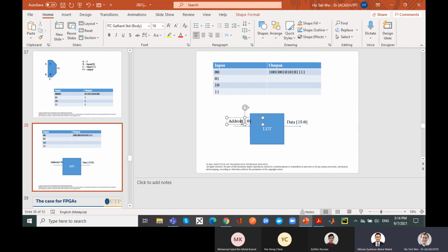Register, Doctor. Register, it looks like a form of ROM or memory, right? Not quite register. Register is actually another word for a single flip-flop, but you are on the right track. This actually looks to you something like, I think your word is ROM, because you can't write it, right? It's already saved, or it's a kind of memory, all right? It's a kind of memory, right? You put in the address, the data. So you can actually implement a lookup table with a ROM device or a memory, correct? You use the inputs as the address and the output itself is the data. Agree with me?